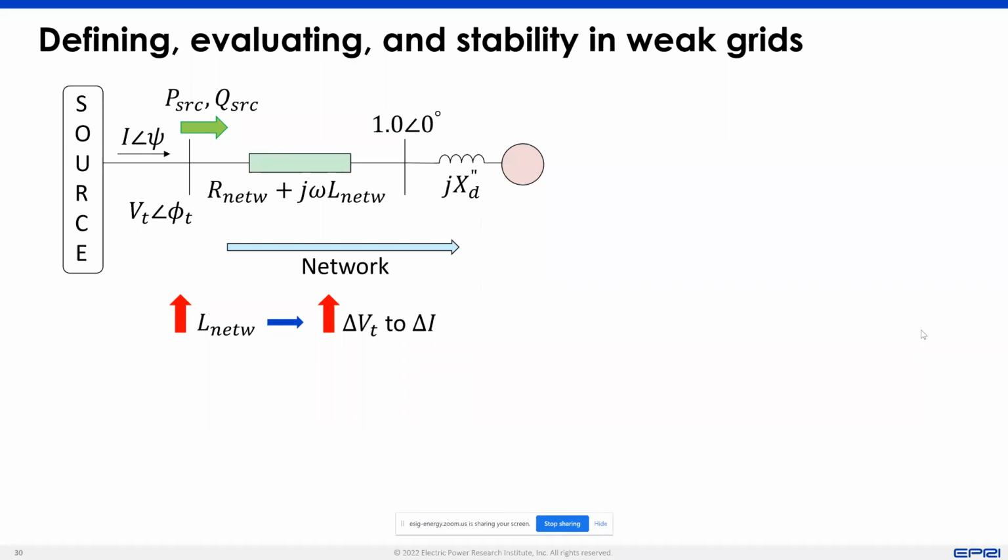So this is going back to the cartoon figure that we had in the initial slides, wherein the voltage starts moving around faster or more when you compare it to the injection of current. So the small changes in this current injection will cause larger changes in this voltage as this impedance starts increasing, because there's nothing to hold that voltage down.